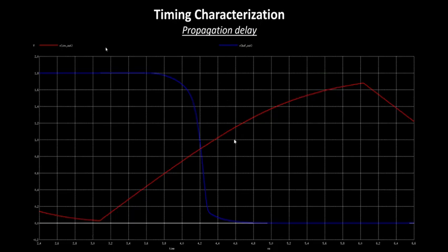If you see this particular waveform is your input waveform, from the slew of the input waveform, you can figure out that the wire delays are pretty high. This could be one of the reasons where, in your layout, the two inverters are placed very far apart. You remember that we have seen a layout over here. The two inverters are very far apart, and you have a huge wire between two inverters, and that might lead to the output of the first inverter giving such huge slew.